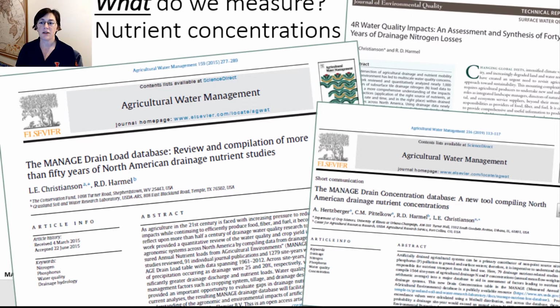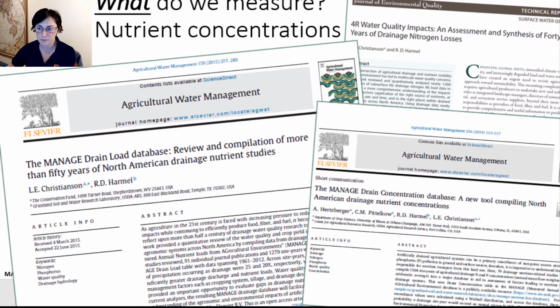Now that we've talked about what concentrations are, the next natural question is, well, what's a kind of normal rule of thumb nitrate concentration in our tile drainage water? Several years ago, I did a large-scale review of, to my knowledge, every published drainage water quality study from North America. We compiled all of the information from all of those studies in a database, and then I had a student add to this just a few years ago.